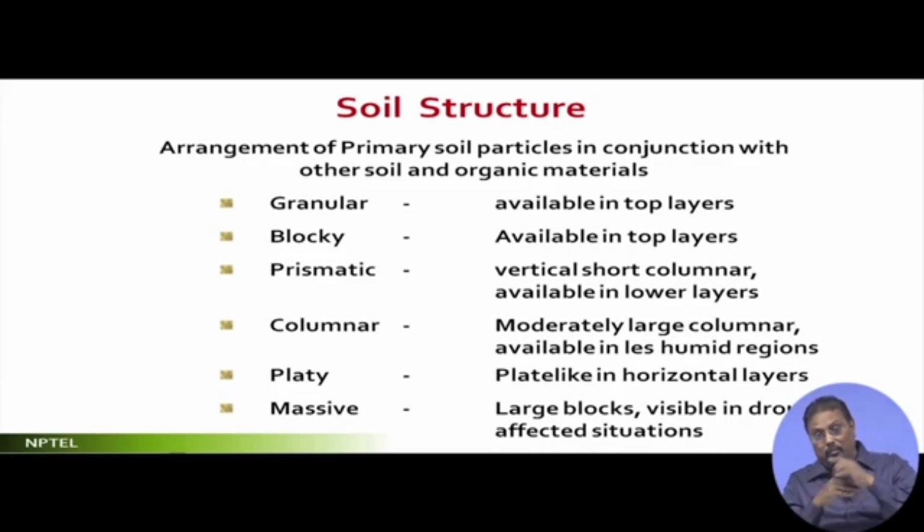So you don't have to worry about it, but I do worry for one reason. Since it is platy, if there is creeping of water within, the individual plates are held together by in-between components, and those components are not strong enough to hold each other because water has crept in and made it almost like a lubricant. Then the micaceous particles start dissolving into the water, and at this intersection point it becomes a dissolved, sticky lubricant. In such a case, the plates slide against each other, and once the plates slide, the stability is gone. So structure matters a lot.